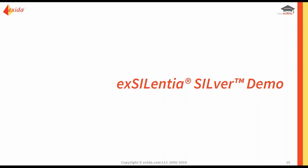So each safeguard has an ID, it has a tag, it has all sorts of information. And if you want to view the analysis and design information side by side, you can do that right here, as I showed you earlier. And so this is a good way to not only have all of your information in one place, but compare: is your intended mission time matching your design mission time, startup time, demand mode, etc.? Is your required SIL and RRF achieved? That kind of thing. And so it's very cool, but as you go through the life cycle, this is built upon, and you can reference it here at any time.